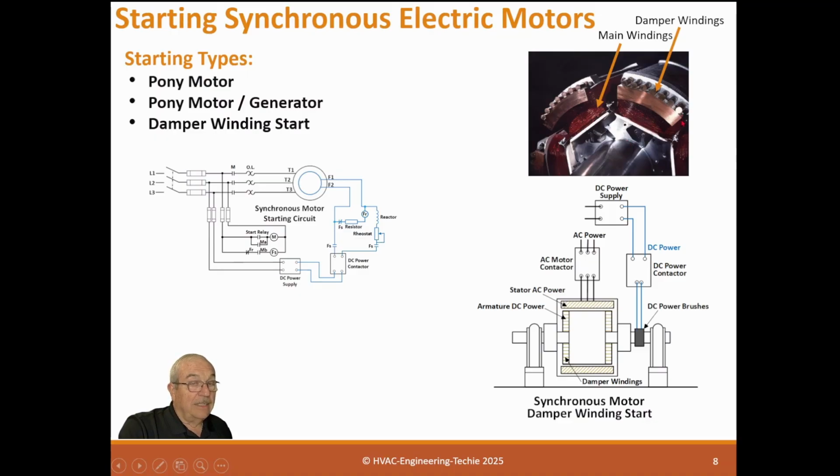It's not. But it acts like an induction motor while it's starting up. So when it's starting up, it powers this up, and this is disconnected, and this rotor starts turning because it's an induction motor for these pieces. This little piece on top here is the induction motor. These coils underneath are the main windings for the rotor. These windings on top are in the induction motor, or the damper windings.